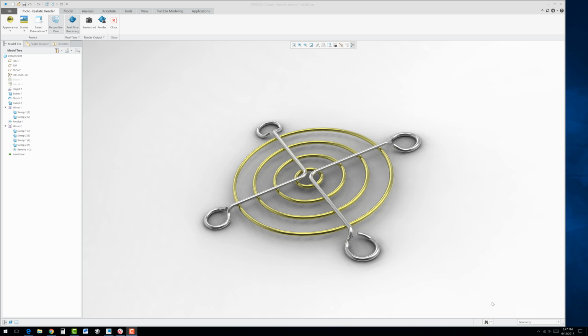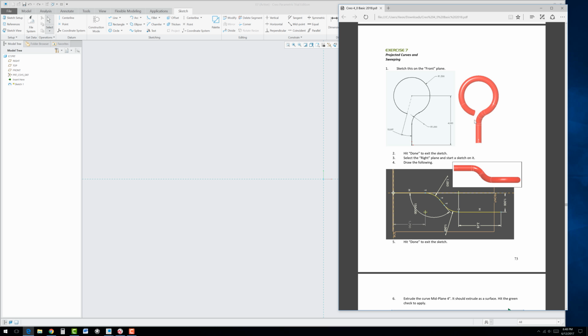There are some additional functions that I show you later on which are very helpful, I think, but for an advanced user those things you probably are going to know already. But here we're going to first make this front view. As you see here, it looks kind of like a question mark almost, and then we're going to make a side view and make the tool to bend the wire on there. So you can see it's about 4 inches in height, 1.5, 15 degrees, and 1 inch radius.